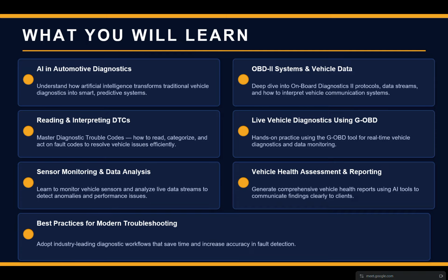So, when we are diagnosing a car, because we're in the 21st century, the first thing we want to look at is the fault codes, and then after the fault codes, we want to look at the live data. All that data together, you are now going to compare with the fault you are trying to fix in the car.